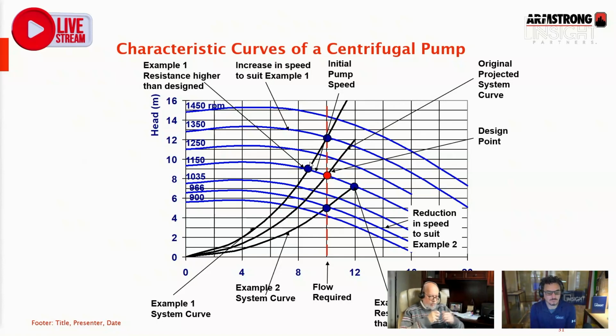One of the best examples, when I was working as a consulting engineer: they started the system up, and the TAB contractor called me up and said, "Man, we got a huge problem. The system head loss is like 2.5, 3 times higher than what you showed on the drawings." And of course, we're not getting the right flow because we moved way back left on the curve. And we got big problems. The water source heat pumps aren't working right, and all that.